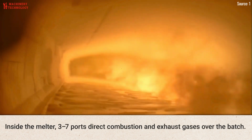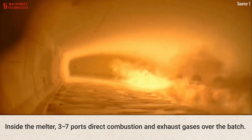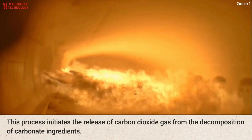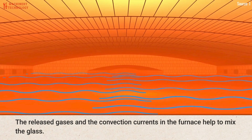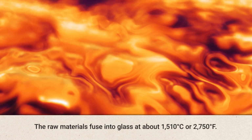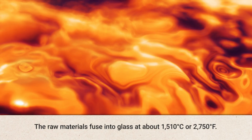Inside the melter, 3 to 7 ports direct combustion and exhaust gases over the batch. This process initiates the release of carbon dioxide gas from the decomposition of carbonate ingredients. The released gases and the convection currents in the furnace help to mix the glass. The raw materials fuse into glass at about 1510 degrees Celsius or 2750 degrees Fahrenheit.